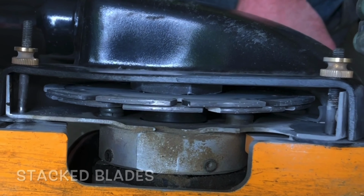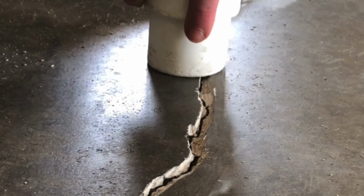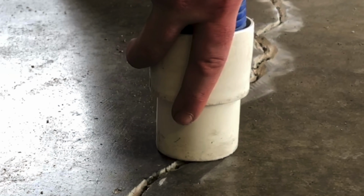So if I have a crack that, let's say, is 1/8 of an inch, as an example, I would probably want to widen it out at least to a quarter of an inch, maybe even more. It just depends on how wide the crack is. It depends also on the equipment that's being used, because cracks don't usually take place in a perfectly straight line. A saw blade is a perfectly straight tool.